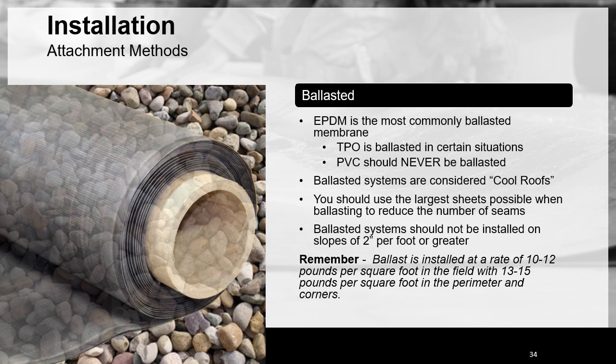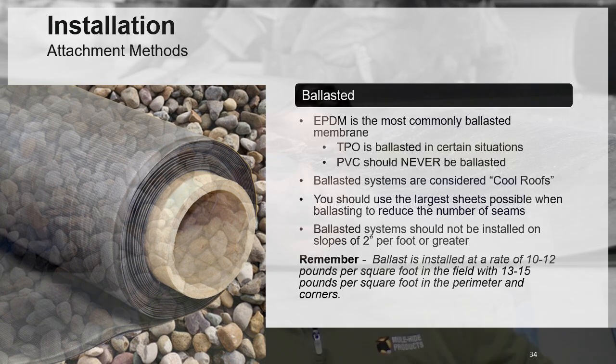So it's a pretty simple system. You put the membrane down and you pour a bunch of rocks to hold it on, right? So I'm sure if anyone stayed at a hotel recently, you have that beautiful view of a roof, you see all these rocks and you're thinking, what the heck is going on? Well, that's literally what it does. The rocks hold down the entire roofing system, which is an archaic system. People generally don't do that nowadays, but you do come across it pretty often.